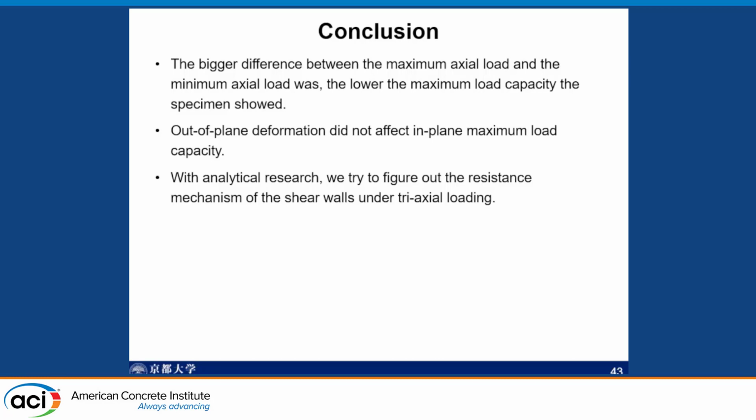So as the design equation suggested, of course the axial load had much influence on the capacity of the wall. And then the out-of-plane deformation did not affect the in-plane maximum load capacity.